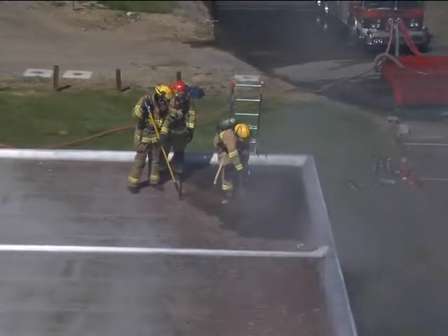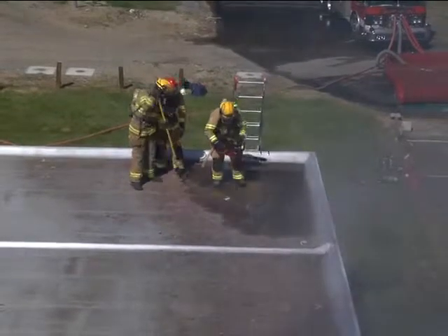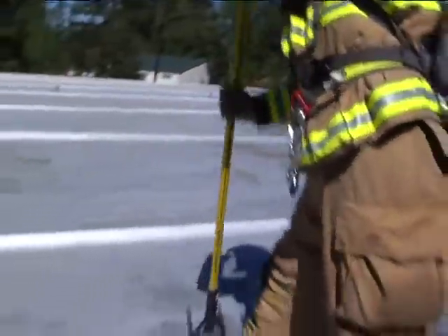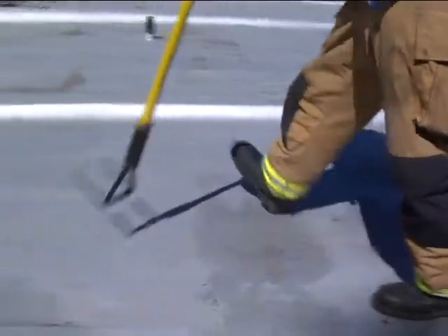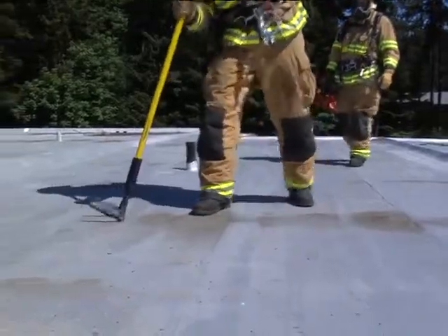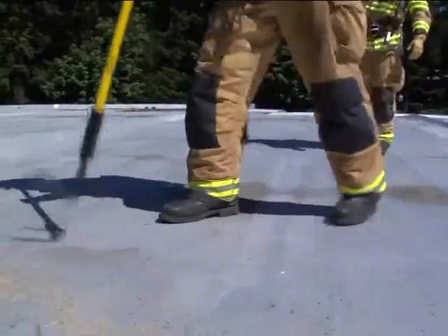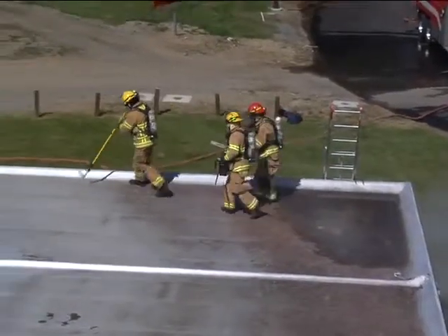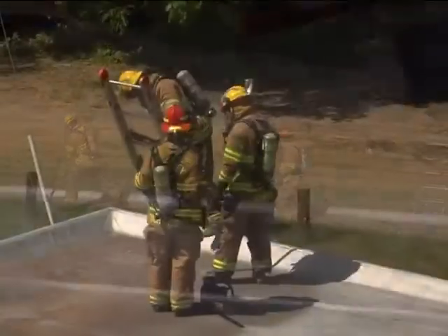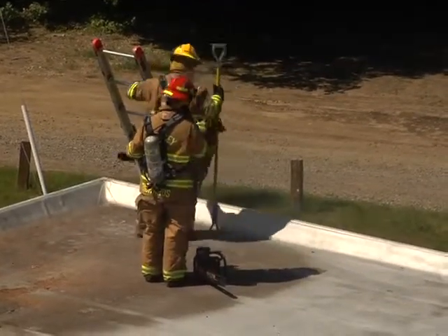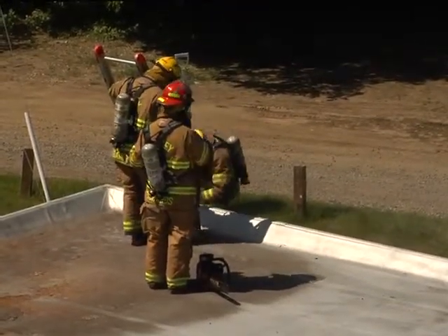Keep your 2 escape routes in mind and have a plan for how you will get to them. Use your axe or other tool to sound for supports or rafters. The tool will bounce on a hollow area and will sound dull and solid on or near a support. You should be continuously assessing roof conditions for safety. Always plan your escape routes and leave the roof as soon as the job is done.